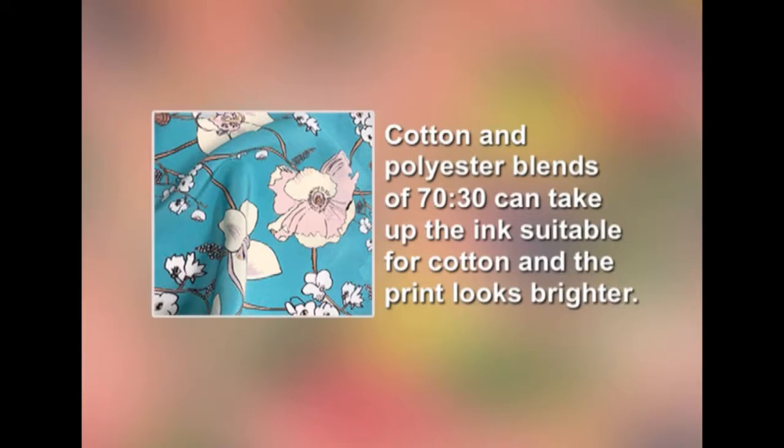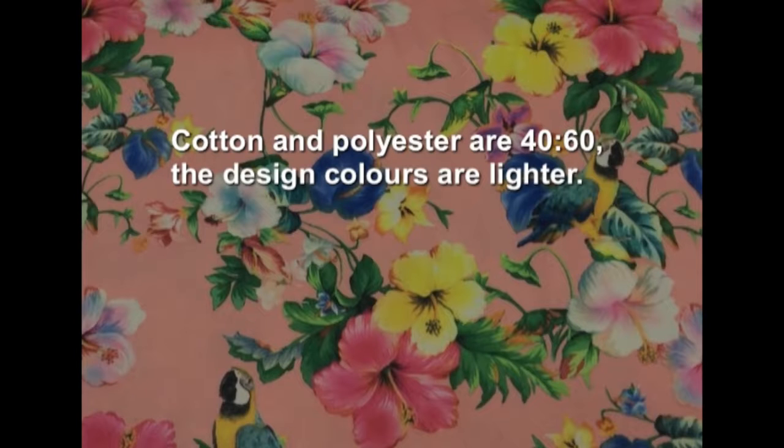For example, cotton and polyester blends of 70-30 can take up the ink suitable for cotton and the print looks brighter. In the same combination, if the cotton and polyester are 40-60, the design colors are lighter. Among natural fibers, woolen fabrics may pose a difficulty in printing, as the high quality printing heads are damaged by the protruding fibers on the surface of the fabrics. Both woven and knitted fabrics can be printed in spite of the stretchability of knitted fabrics. Other blends such as cotton viscose, polyester lycra, polyester wool, polyamide lycra, silk blends can be printed by selecting suitable ink that goes very well with the particular fiber.